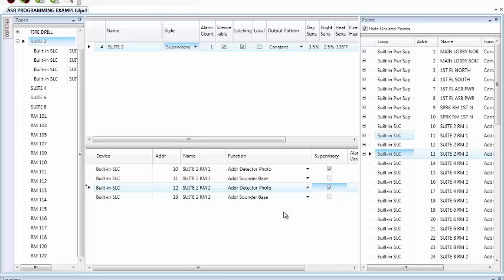So this scenario is best used when there is a fire alarm control panel that is monitored 24 hours a day on site. For example, a hotel usually has the fire panel very close to the reception desk, and there's usually a person there all the time. Again, this needs to be cleared with the authority having jurisdiction, the AHJ, the building owner, as well as the fire marshal if that is not the AHJ. But you can set them up as a supervisory.